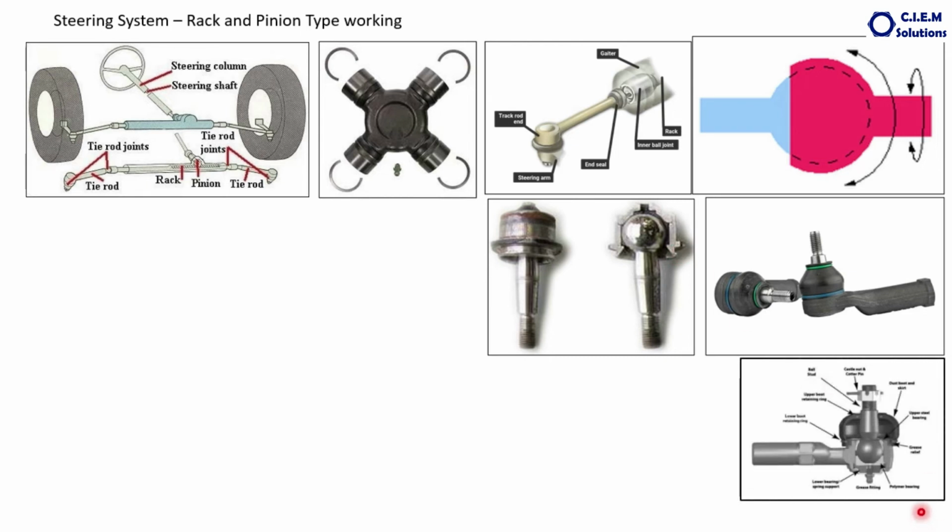If you look further elaborately, these are the various components of the ball stud. There is a rubber cap to arrest the leakage. There is a nut. There is a stud. The ball. This is the polyethylene cup, which is strong enough to take the friction. And this end is with female thread. This is about the ball stud.